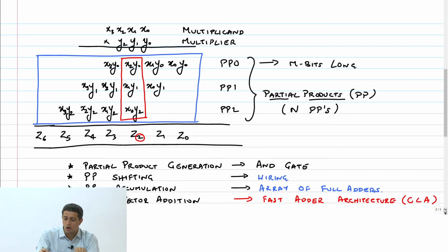Yeah, we will come to it when I show you the implementation using full adders. You will find that there is one final addition that needs to be done. Okay, in the sense, you put these arrays together, put enough number of full adders. Suppose you are doing 4 cross 4 multiplication. You put 16 full adders in this so that you can do this multiplication addition appropriately. You will find that the last stage just turns out to be a ripple adder.